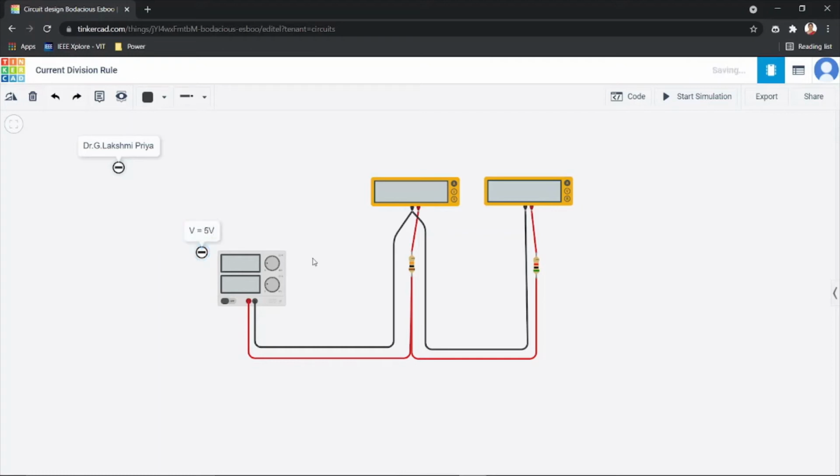Okay, and then we have our resistance. So this we need to name. Again, we have to pick up this node here. Just click on that. You can just type it as R1 equal to 10 kilo ohm. Fine. If you want to copy it from your WordPad or your Word document, you can even insert the symbol here. Here the symbol insertion for the nodes is not available, so I've just written it as kilo ohms.